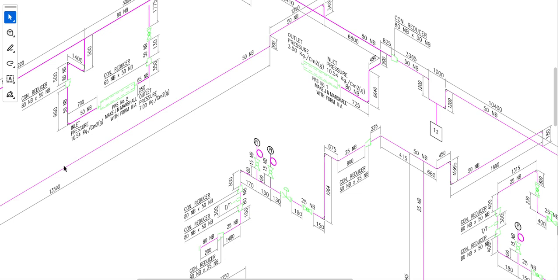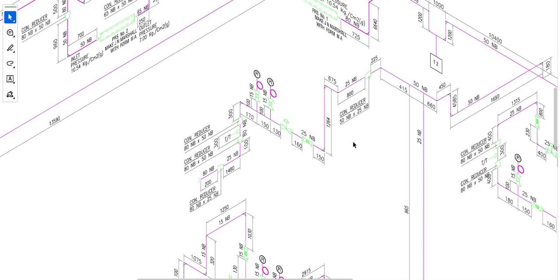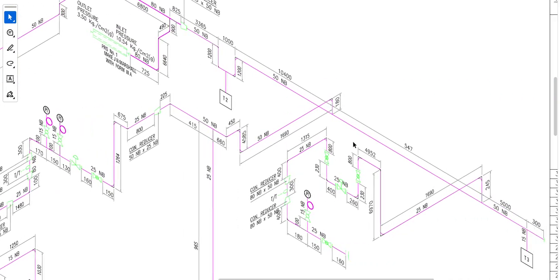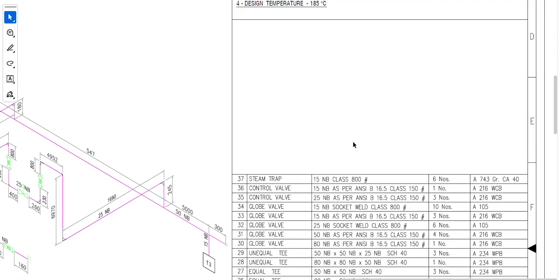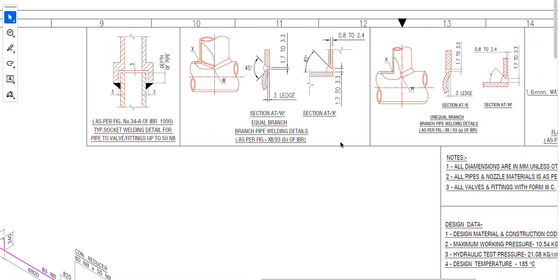In the plants, this line lays on the pipe rack, and from the pipe rack we have another PRV station which goes to the particular equipment, and then other lines which are the source of supply to the particular equipment. The isometric covers all the sight glasses, reducers, valves, pressure gauges and everything, to be mentioned as per actual. The isometric also covers the type of supports which we use.